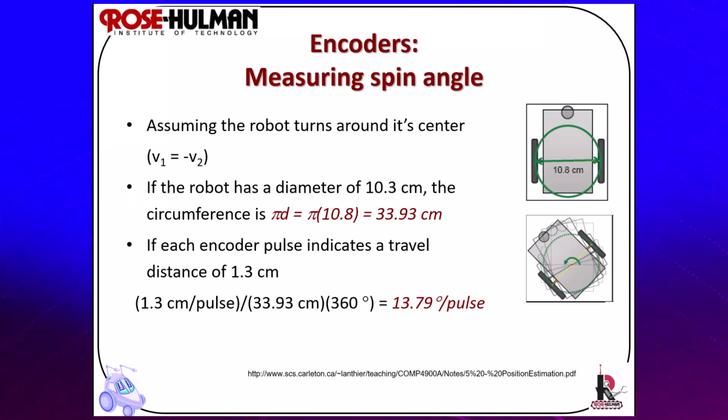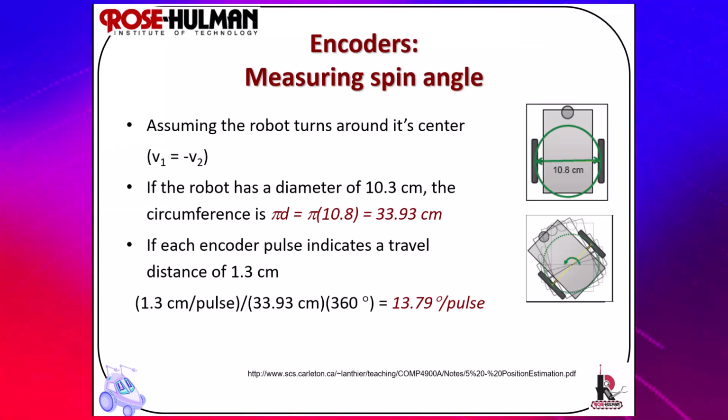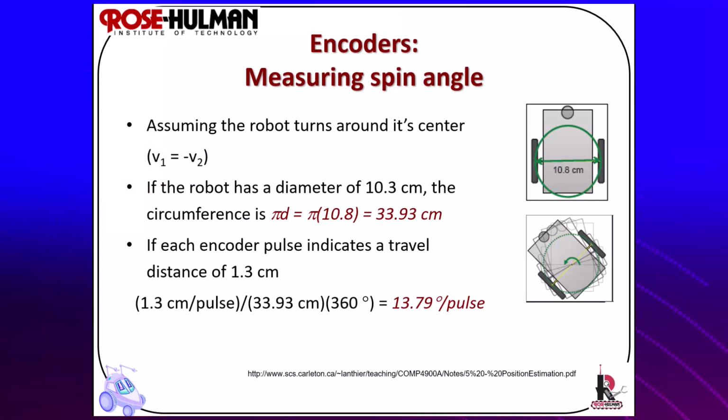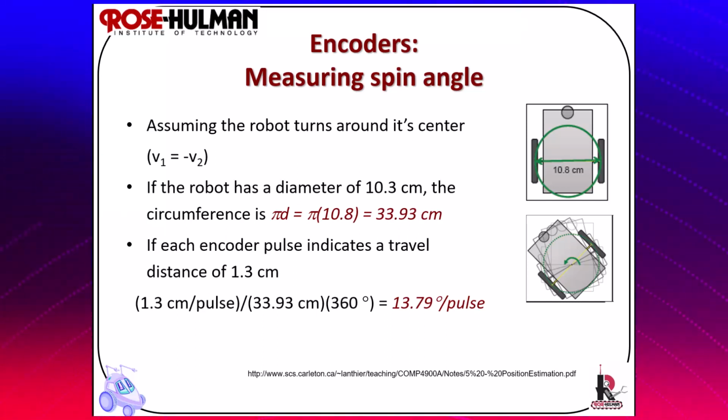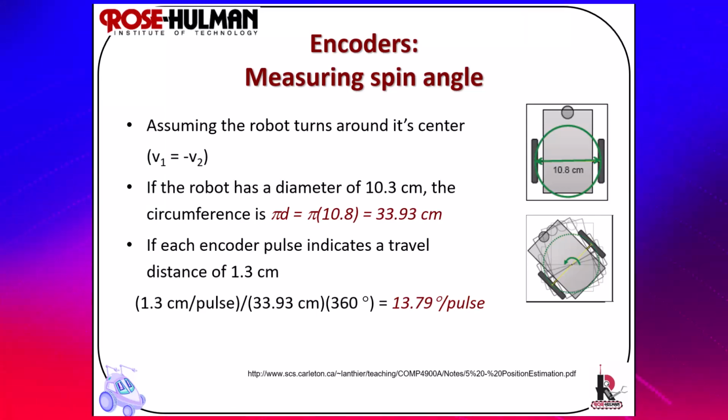You can now use this along with your commands to estimate how far the robot turns based upon encoder pulses, or you can use stepper commands and then use the feedback from the encoders to correct for turning error or angles as part of that odometry error.